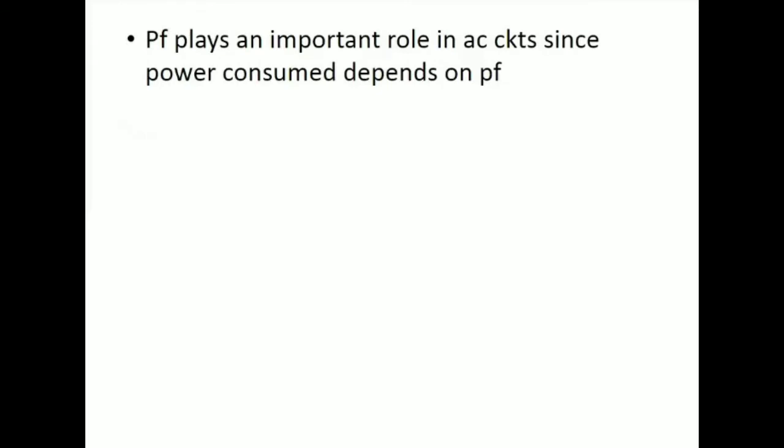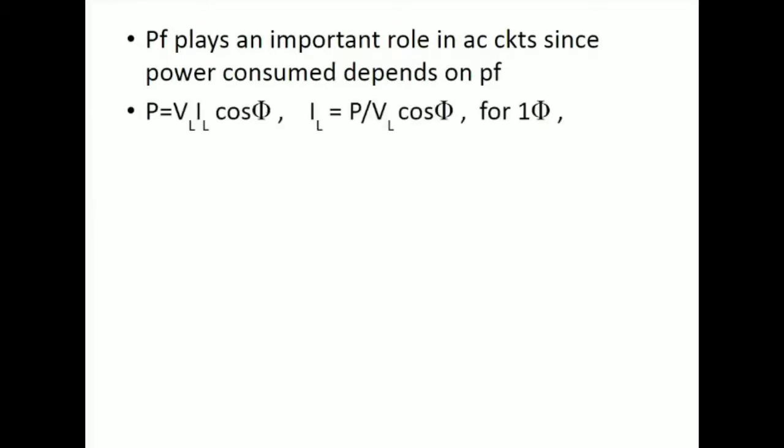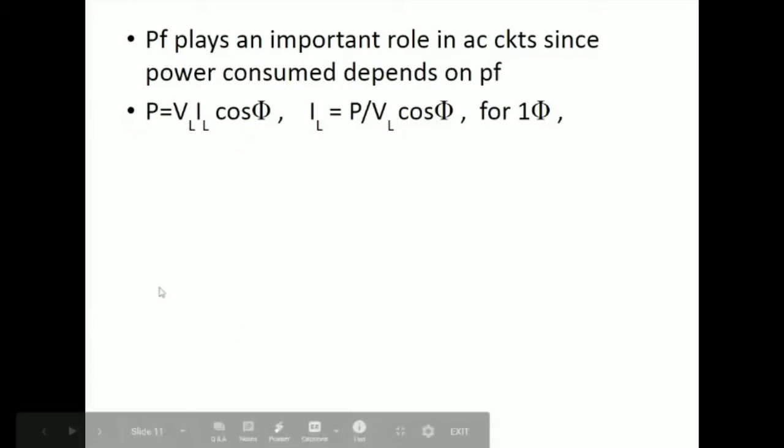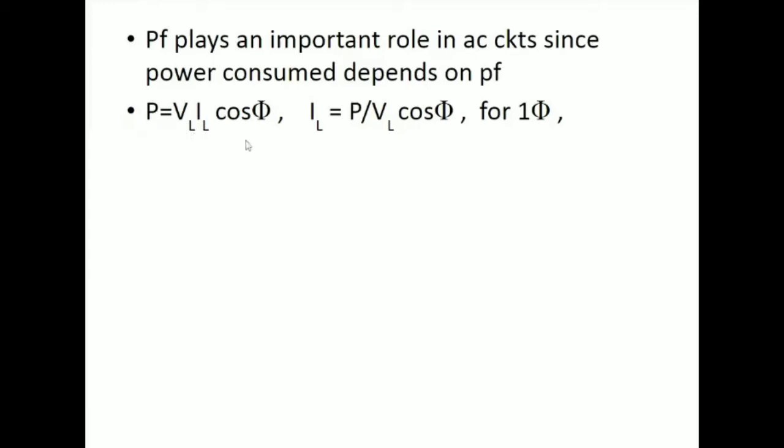Then what is the importance of power factor? Power factor plays an important role in AC circuits since the power consumed depends on power factor. We know that the active power is the actual power consumed. It is also referred to as real power. Active power is given by VI cos phi. From this you can find out the current.